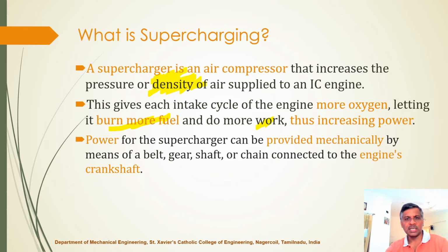But the problem is the power for the supercharger. The power to run the compressor is provided mechanically by means of a belt from the engine crankshaft itself, from the engine itself. So you are losing a major amount of power to run the compressor. That's a problem in supercharging.